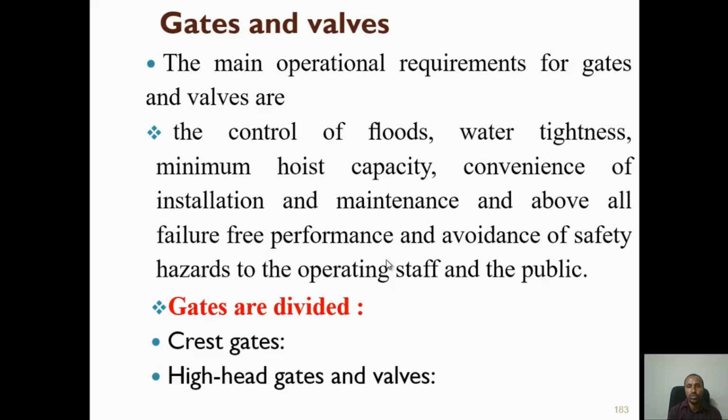During sudden opening or sudden closing of the valves, water hammer may be created. The pressure may travel back, and if the penstock is not strong enough to withstand the internal pressure laterally, it will be damaged, and then leakage may happen.